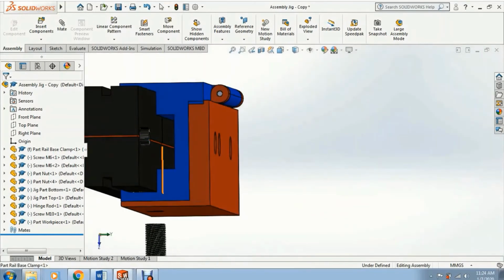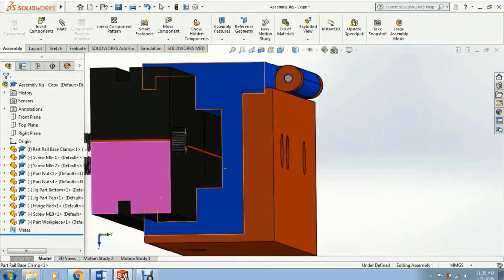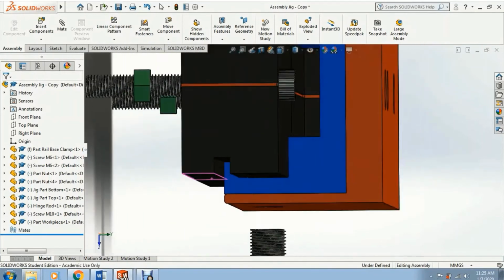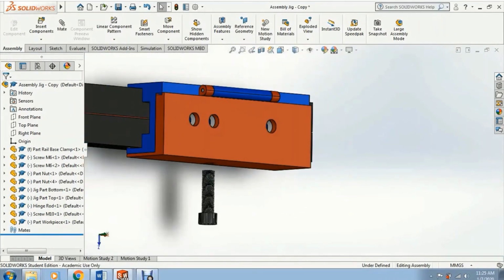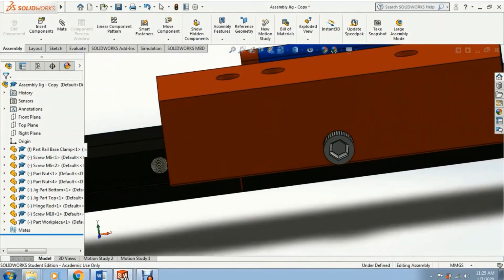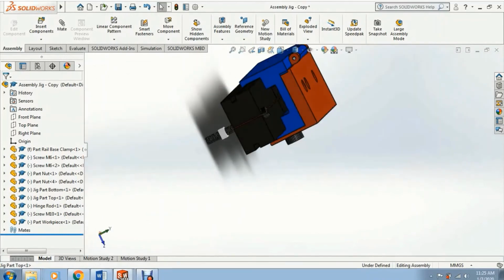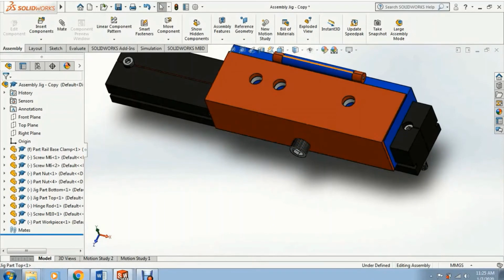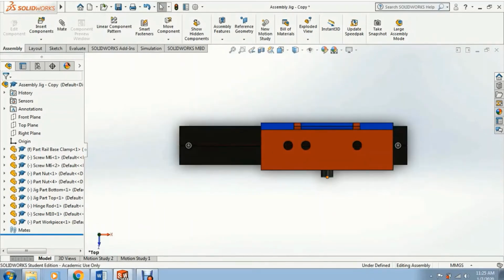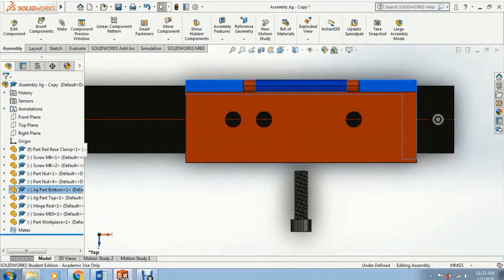And then, okay, this is what I say here, to restrain the chips from interfering with the body movement on the rail. So this is the rail mechanism. It is in there, and then we'll close, and then we'll insert the stopper. When we insert the stopper, the jig will be fixed, and it restricts all the degrees of freedom. Okay, and then for the second, pull out the stopper and move the jig to the second hole.